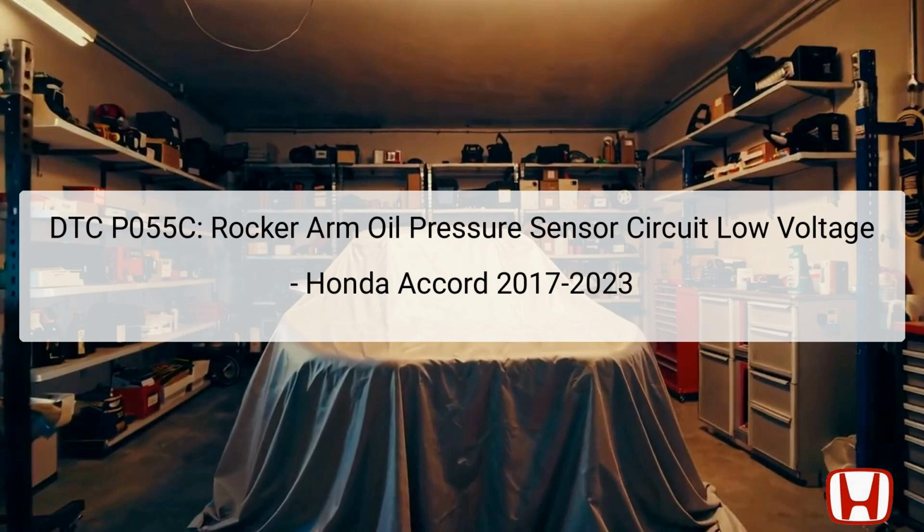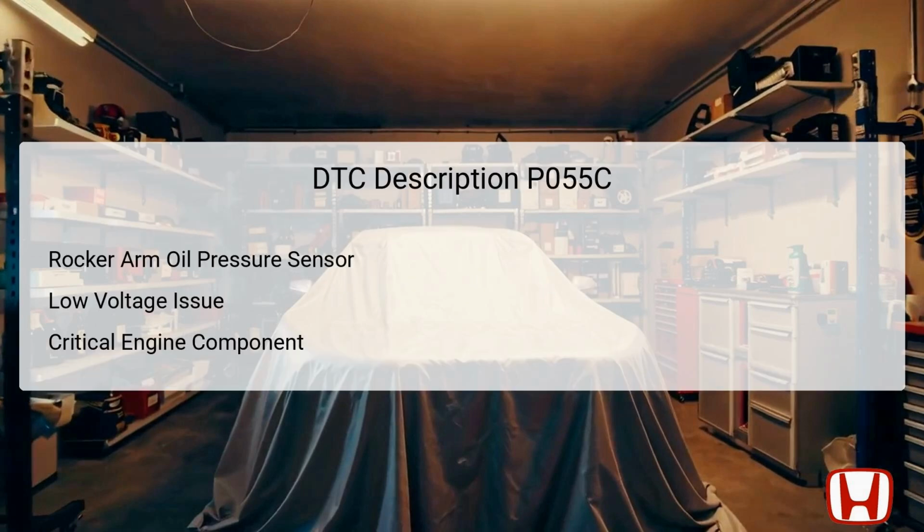This troubleshooting guide will systematically address potential causes and repair strategies for resolving this error in the Honda Accord models spanning 2017 to 2023. The DTC P055C specifically refers to issues with the rocker arm oil pressure sensor circuit showing low voltage. The rocker arm oil pressure sensor, crucial for the engine's performance, measures the oil pressure and communicates that information to the PCM. When the voltage from this sensor falls to 0.18 volts or less, it raises a flag for the engine management system.